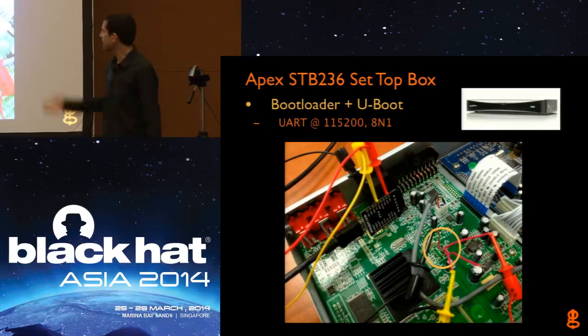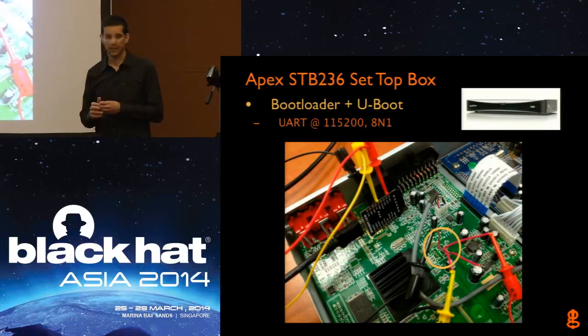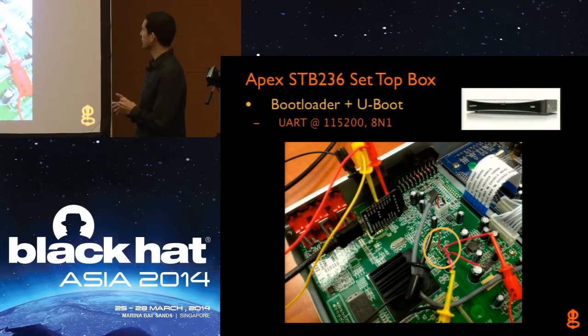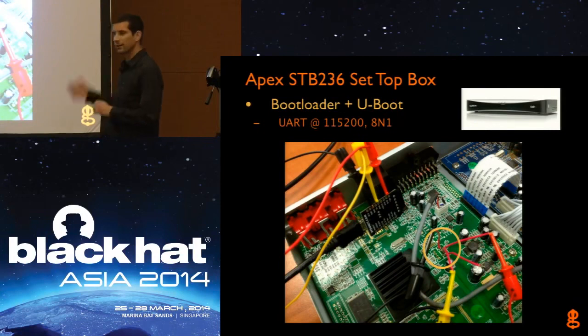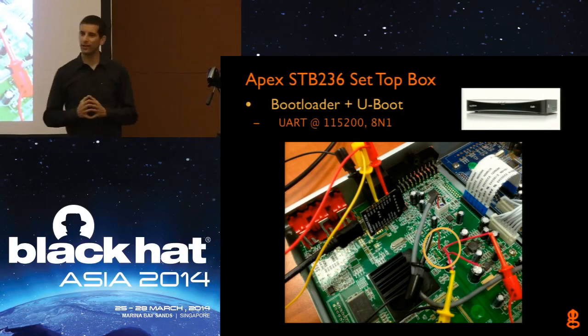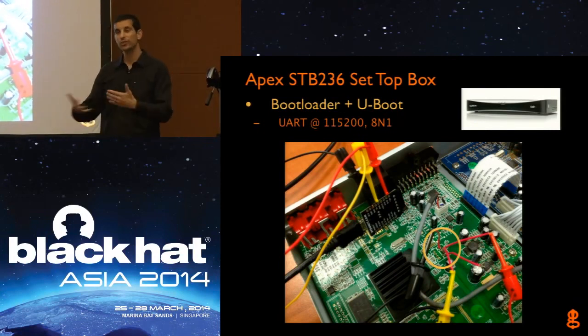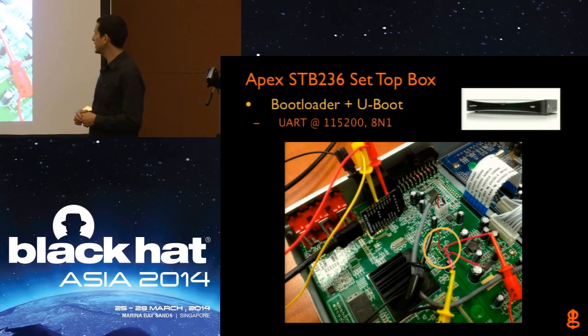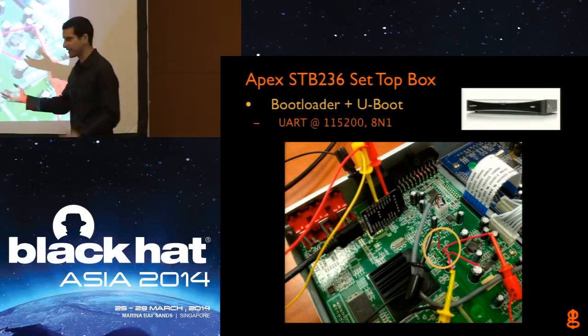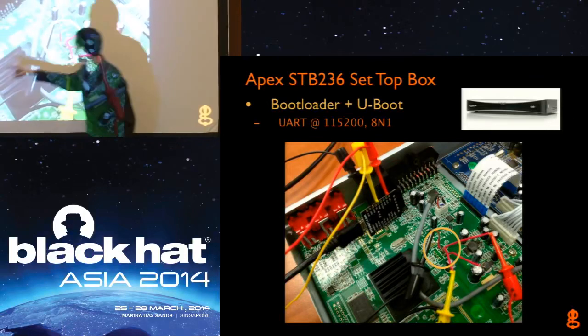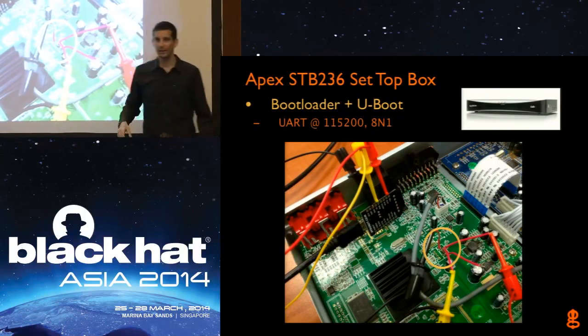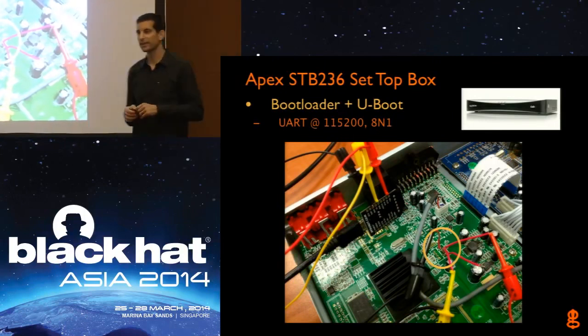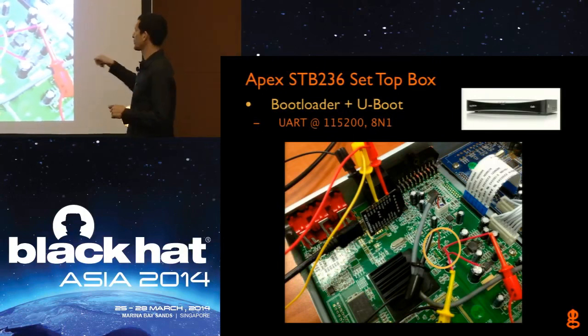Here's another example. Here's a set-top box from Israel. A student had come to one of my hardware hacking classes and said, hey, I've heard that there's some sort of root shell interface on here, but I don't know where it is. Can we find it? So we went through the process of looking on the board, identifying the interfaces, looking for the very obvious connectors, and then poking around with our oscilloscope to find out which one it was.